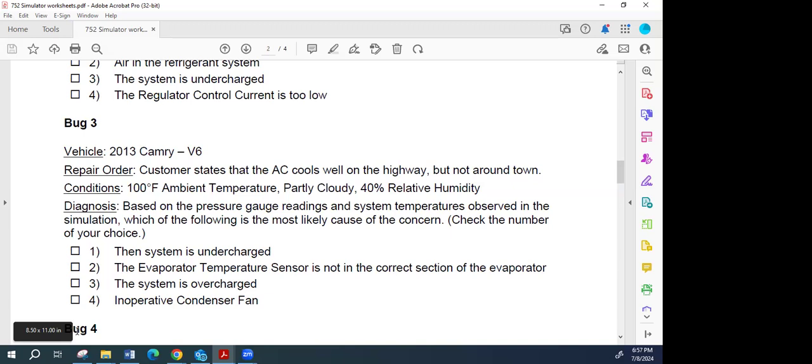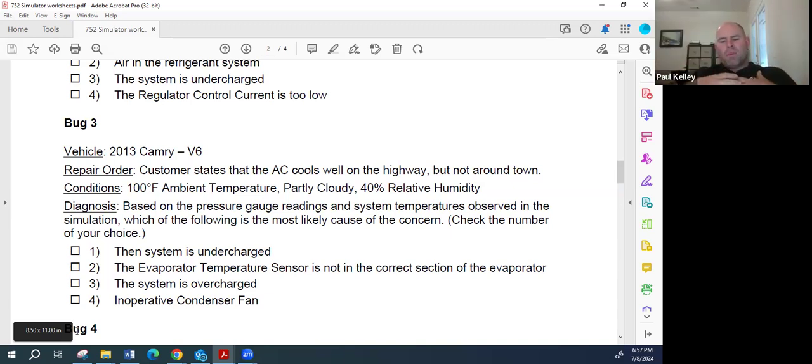That's it. So if my job is to pinpoint the root cause, right? Now, did I see some other things? Yeah. And did I say, well, corrosion on the battery terminals, that could cause some issues? Yeah, that could. However, corrosion on the battery terminals would cause a voltage drop.